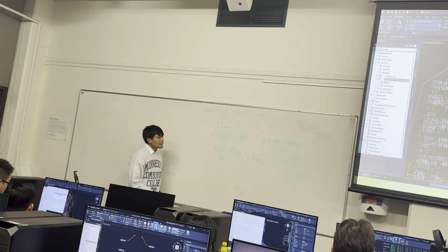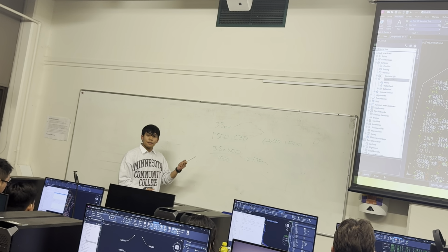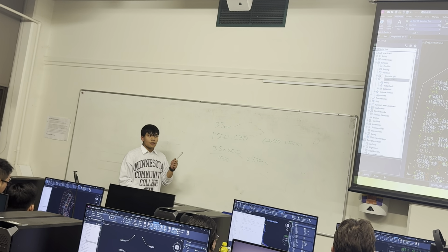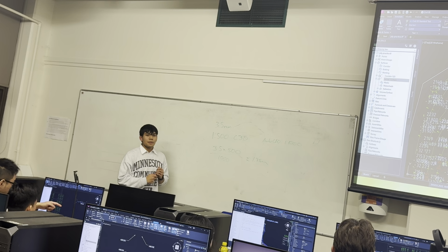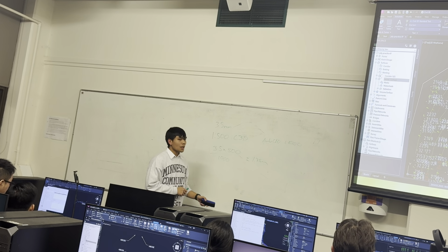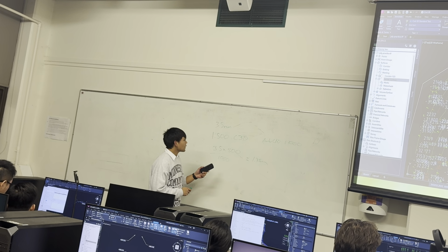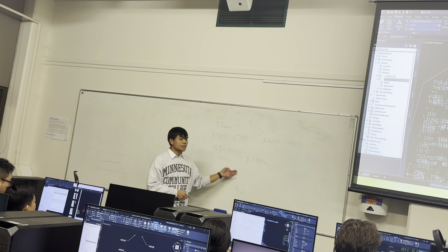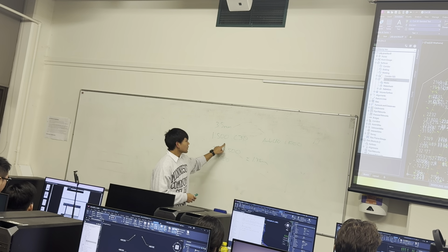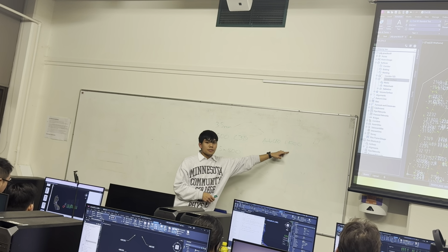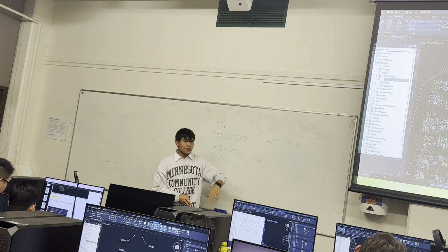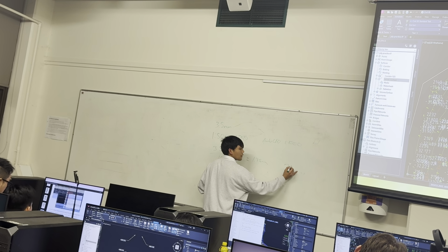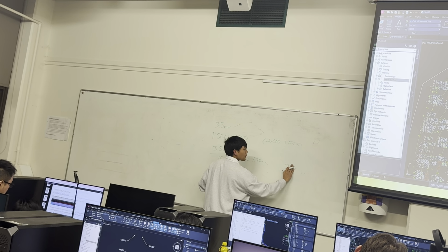For now. But that's going to be different in Part C, because you will have different scaling when you export it, and this might get confusing. When you export it, the text will go 2x bigger. This is because AutoCAD is 1 to 1000. So when we export it, it will become 3.5 again.